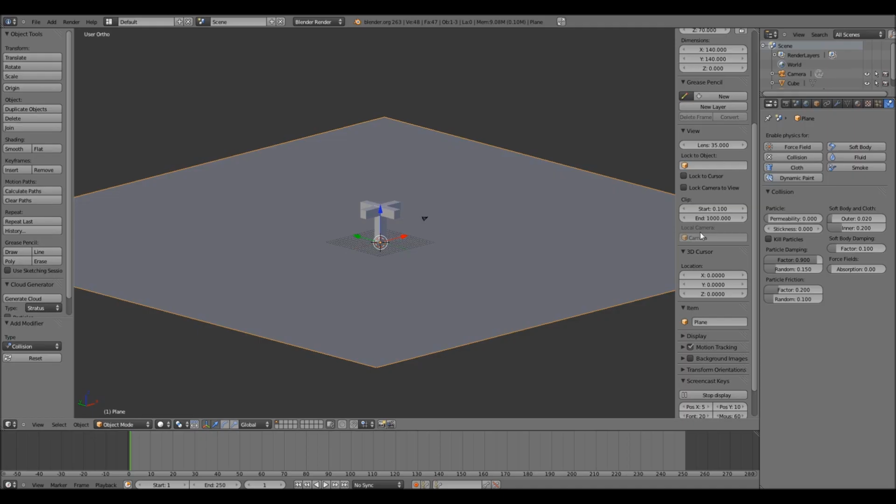In case you're wondering what those other settings are doing, they are not relevant for fluid animation, but the kill particle setting is obvious: whenever there is a collision, the particle will disappear from the scene. Permeability means what is the chance that the particle will get through the object, and stickiness defines how particles will stay on the surface. So more or less this looks the same as damping, but definitely we will not use them for the fluid animation.